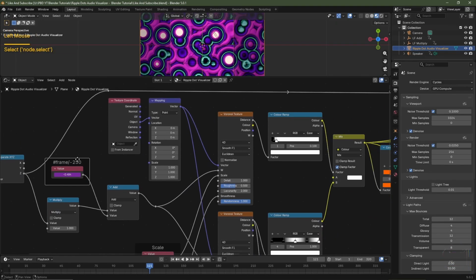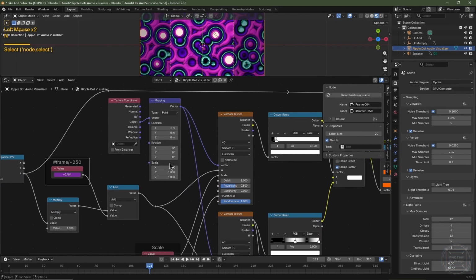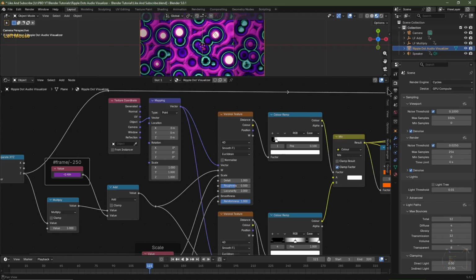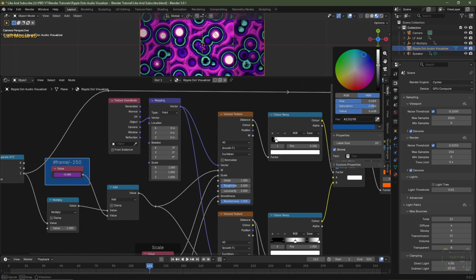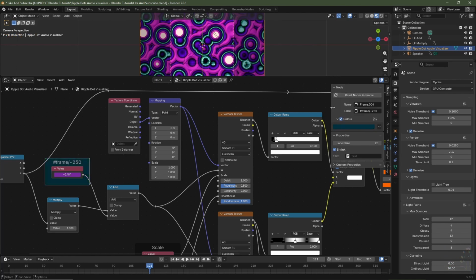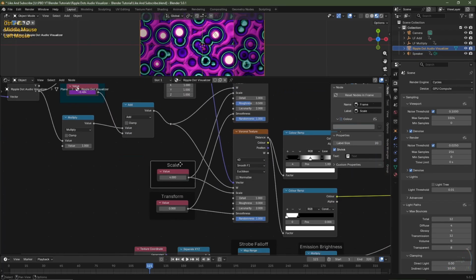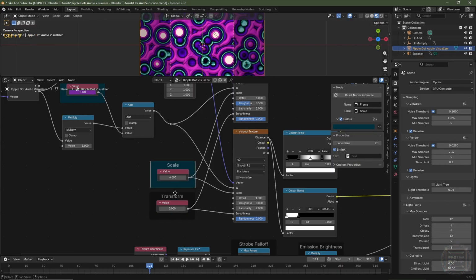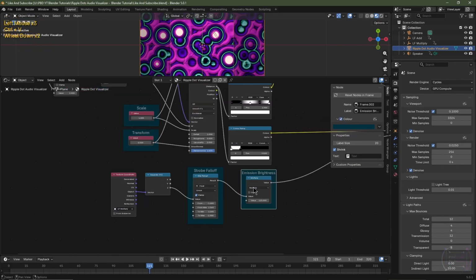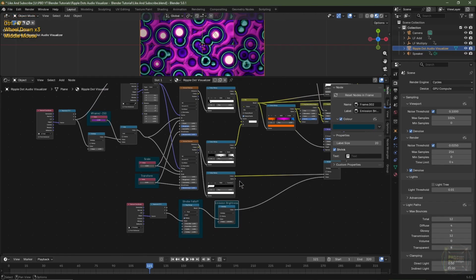And with this frame selected, I'm going to hit N to open up the N panel. Ensure that you've got your node tab selected. I'll then click color. I'll expand these options and I'm going to give this a custom color. Maybe something around, I'll be happy with that. I'll then take my cursor over that color swatch. I'm going to hit Control C to copy that color. I'll then select this frame. I'm going to enable color. I'll then hover my cursor over the color and hit Control V to paste. I'll then do the same for all of these frames. And that's just so we can easily identify the controllers.